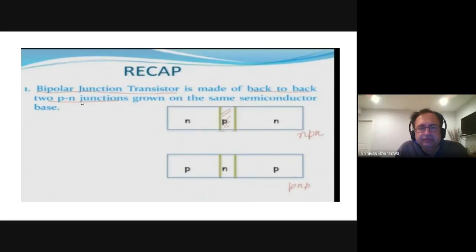Traditionally there is a threshold Vt, and when VBE exceeds that, you then have an exponential relationship, e to the power of VBE by Vt. This exponential relationship means that it is a curve like that. So now, how do you make it an amplifier?